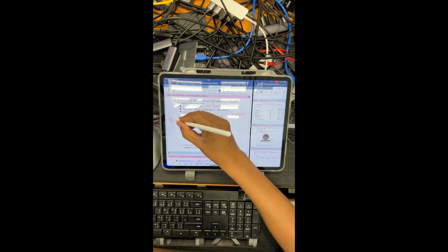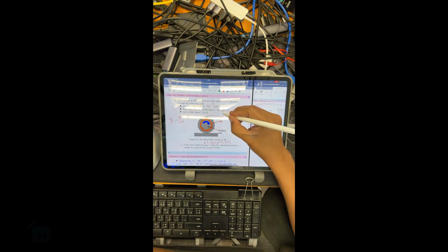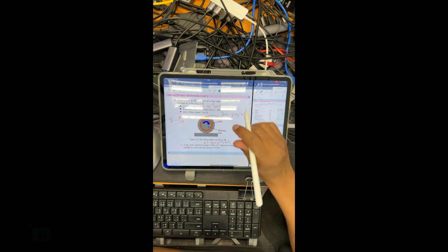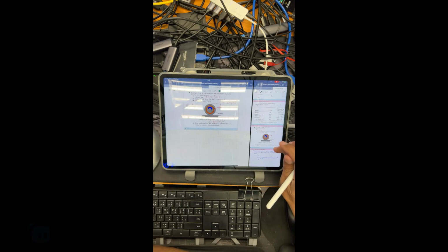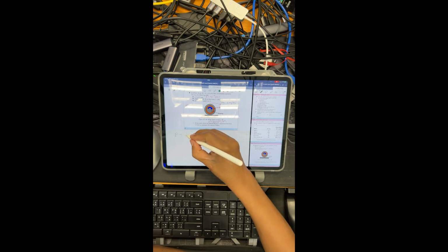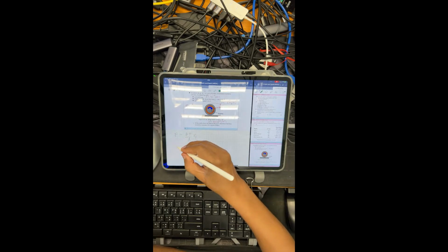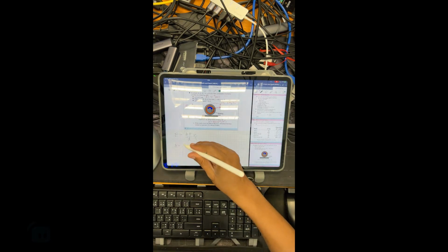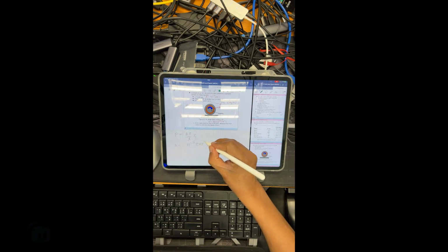Pascal is equal to Newton per square meter. So we have here Pascal times second, and M is the milli, which is 10 to the negative 3. So we start to solve this problem. The formula is F equals A times V divided by D, times eta. What you can see here is that A is 10 to the negative 2 square meter only.